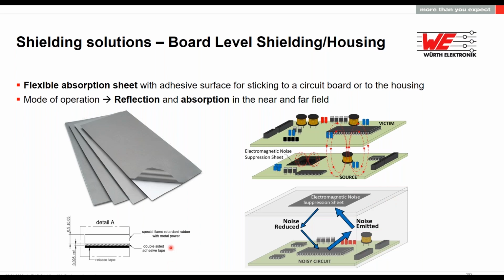It doesn't have any interference because this inductor creates by itself a magnetic field. This is impossible to erase because it's how the inductor behaves. We need this magnetic field because if not, the inductor wouldn't behave like it does. What we can do is to place this kind of absorbers or ferrite sheets in order to prevent this noise or this magnetic field from affecting other parts of our device.